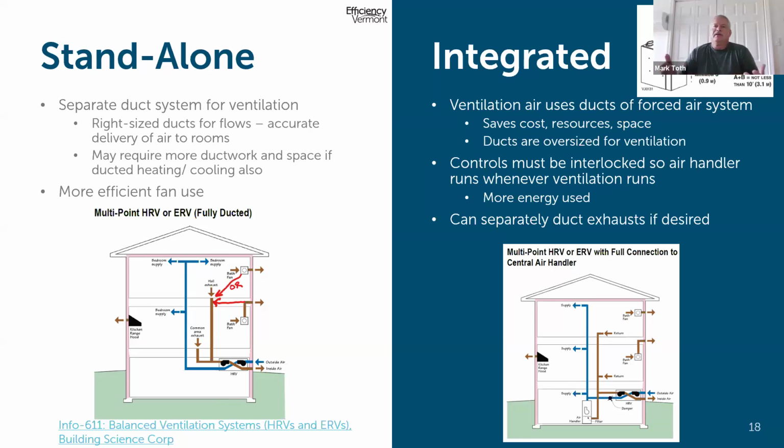So you're going to run your ventilation system, say, either 10, 20, 30%, 50% of the time. So say 50% of the time, you're going to be running the system fan on low speed in conjunction with your ERV, HRV. So you're going to be bringing air into the return closer to the blower, taking air out of the return closer to the return grill.